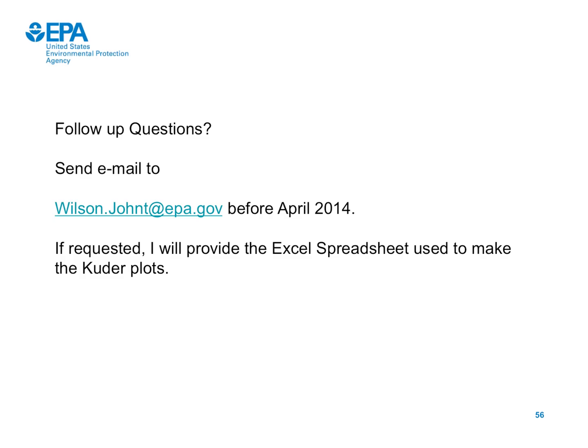I think so. Okay. All right, what's the recommended frequency for CSIA sampling and analysis? Depends on how big your site is and how contentious your relationship with your regulators is. What I recommend people do is they do a relatively small, focused preliminary analysis to see if there's anything that's going to be useful. And if it turns out that you are getting fractionation and that your data might be interpretable, then you go back and you do a more extensive survey.